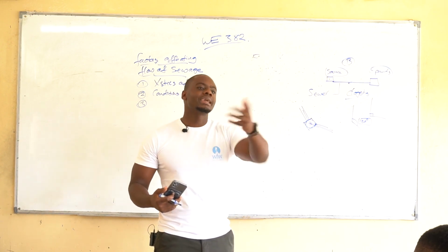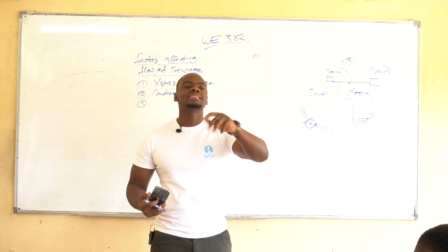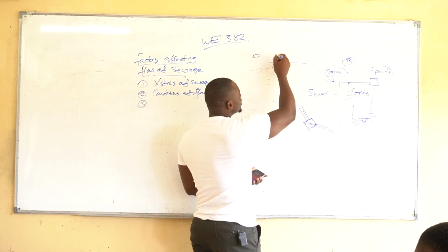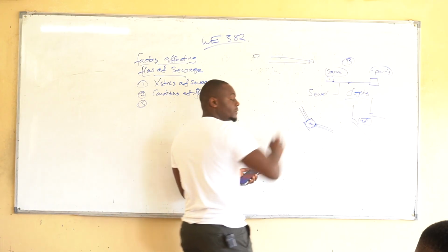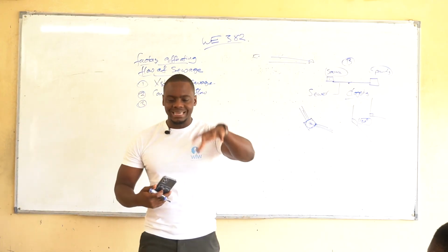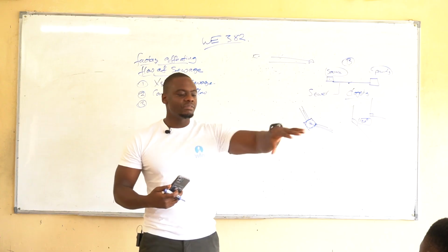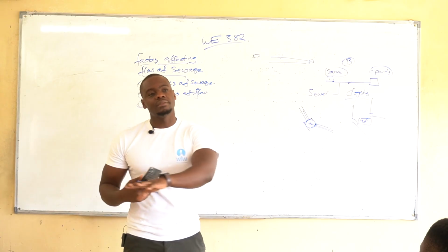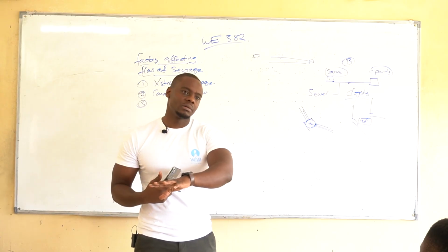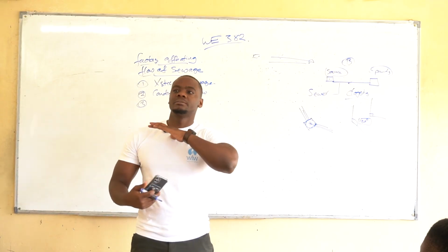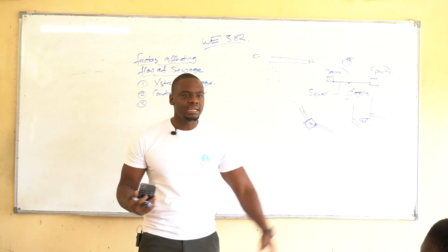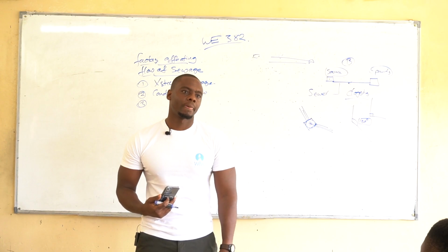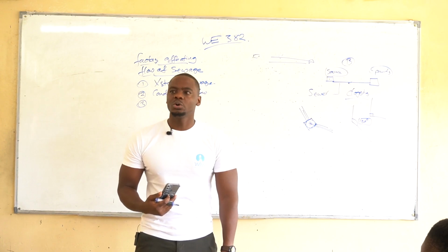But in a case like Western Province, there still could be places that, yes, look that flat, but trust me, there's some gradient of some sort. But then it's up to you, before, let's say, a town is established, to identify which could be a high point where people can settle, and where you can take that effluent or the sewer ponds itself. If it is just flat, you create your own gradient. Okay? Just create your own gradient.